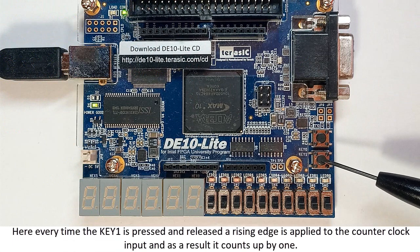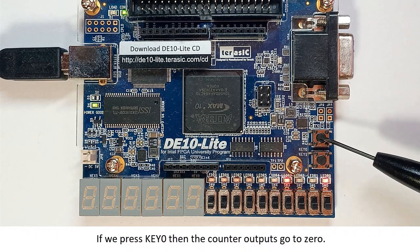Here, every time the key 1 is pressed and released, a rising edge is applied to the counter clock input, and as a result, it counts up by 1. If we press key 0, then the counter outputs go to 0.